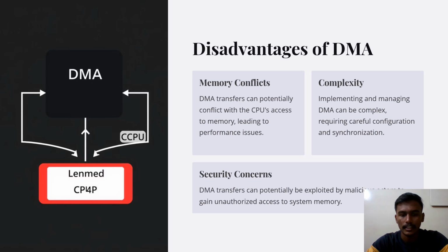Complex hardware design. Implementing DMA requires additional hardware like a DMA controller, which increases the complexity and cost of the system. Potential data conflicts. DMA can cause conflicts between the CPU and peripherals if both attempt to access memory simultaneously, leading to potential system performance issues.